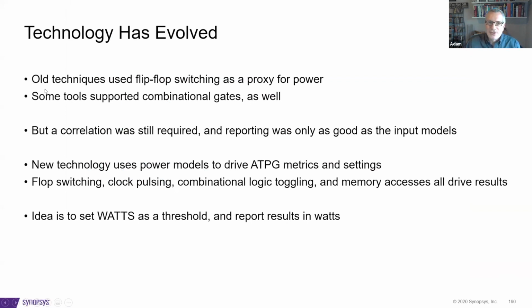So, as I mentioned earlier, the old techniques have used flip-flop switching as a proxy for power, and it's not bad, it's not horrible. Some tools even supported combinational gates as well, but you had to do some kind of correlation, because although you could model, this switches a lot, so therefore, I think it has a lot of power draw. This switches a little, so maybe it's a little power draw. You only get as good as what you're modeling. And if you don't correlate, you really don't even know how much the tool is really using at a particular slice of time on the tester.